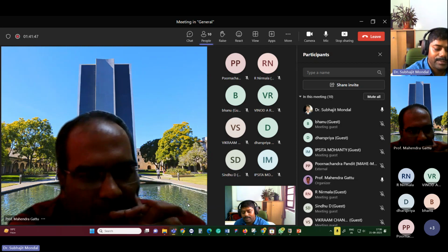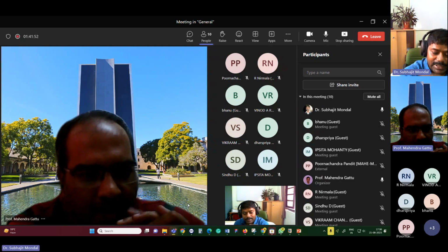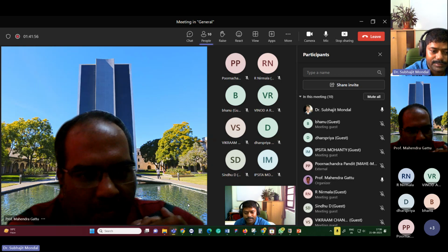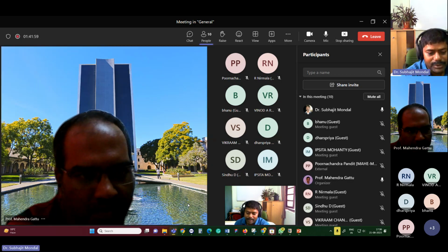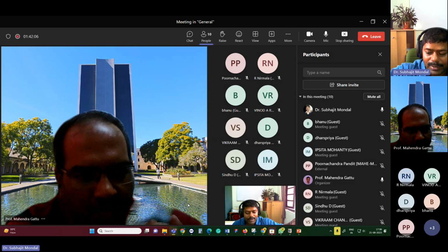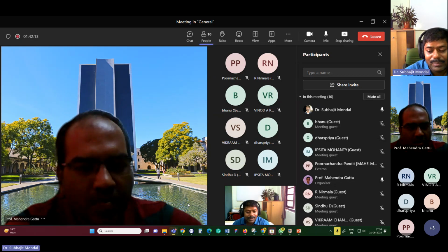The first mode, if you observe, is always a global mode. If you look at your deflected profile mode shapes, the first mode is always global. In the second mode you can have a second curvature, and the third mode has more curvature. So whenever you go for higher mode shapes, you can see a lot of curvature in the deflected shapes. If you go for a higher mode, there is obviously a high chance that it will interact with the damage, and you can easily identify the damage.